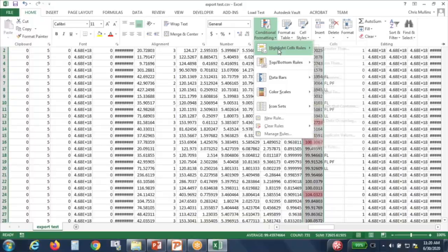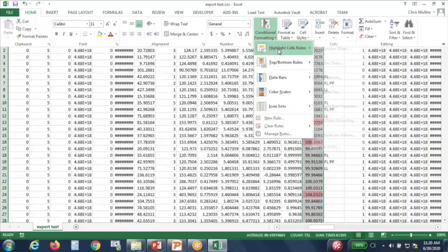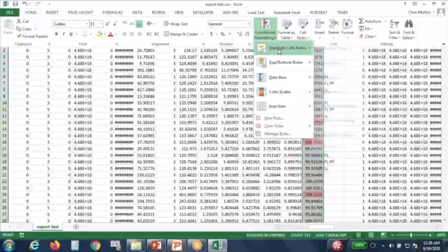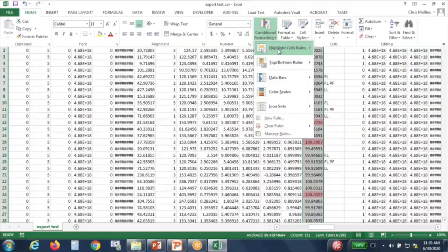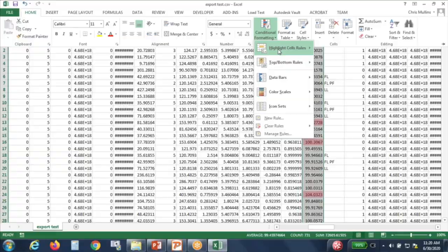Also, I like to look at my current. For a class 20 meter, typically the lowest test point that you test on, the light load test point, is a 1/4 amp. And the meter manufacturer doesn't guarantee anything really below a 1/4 amp, right? At least it doesn't guarantee that 0.2%. So this is another column here, where I've got my current A. IRMS stands for the RMS value for current A, so current RMS value for A, and then B and C. That's what the label is.